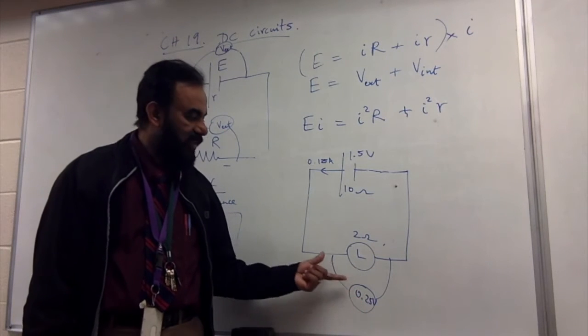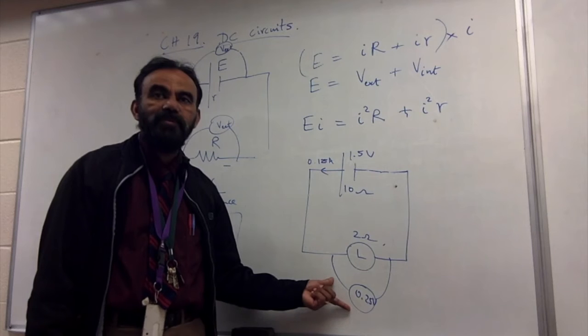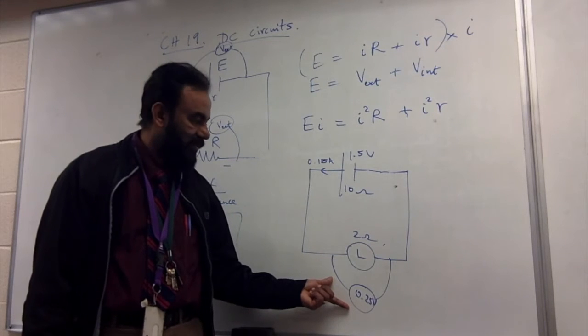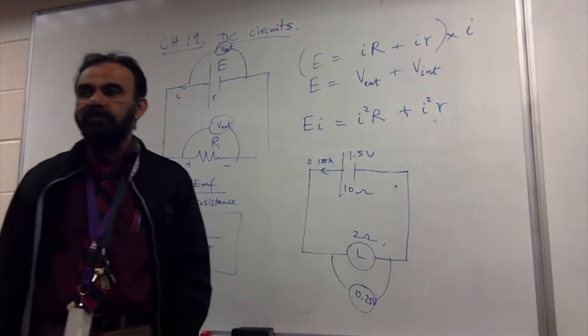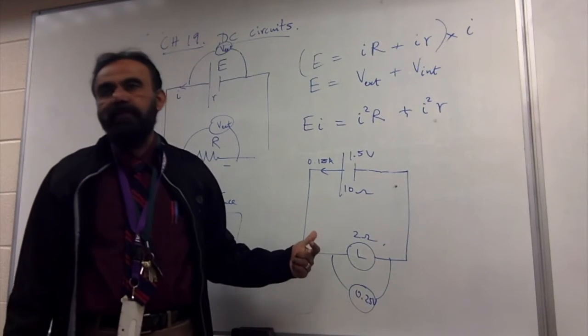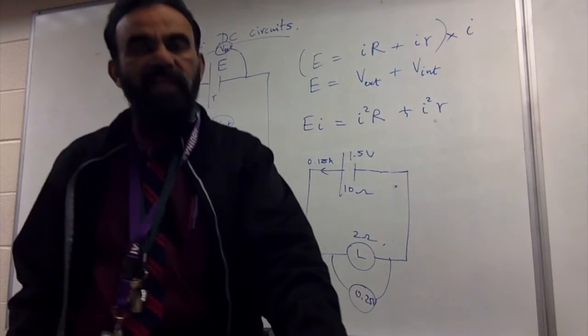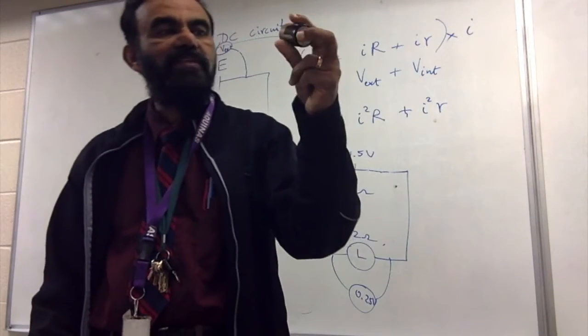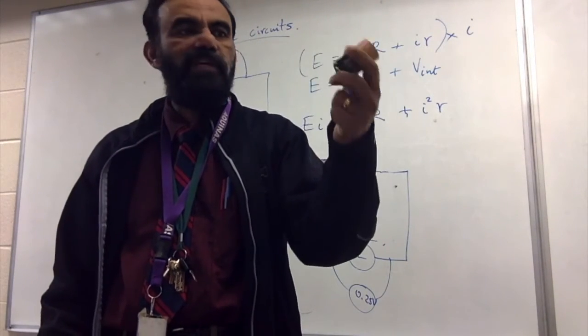0.031 watts is very small. Is it 0.00 or 0.0? 0.0, right? So it is a very small power dissipation, so it's not going to be working. So this cell, once it is used, its internal resistance goes up to 10 ohms and is absolutely useless.